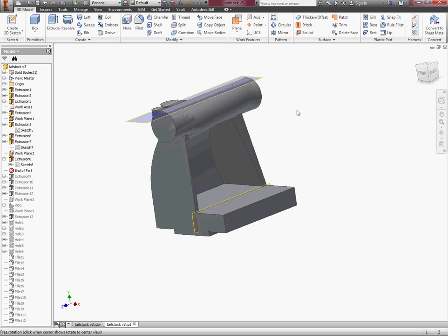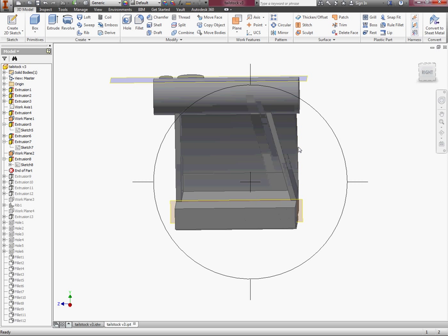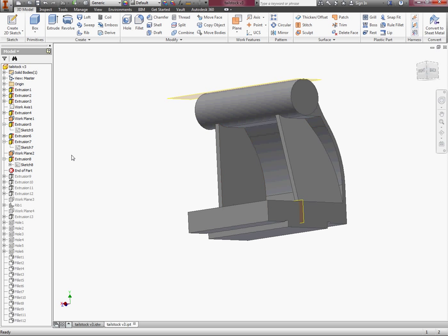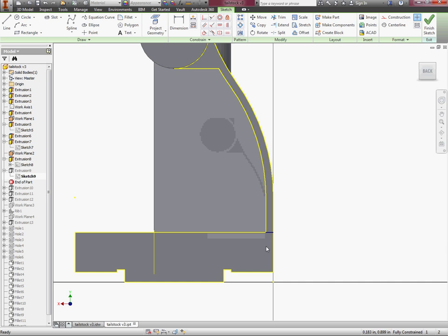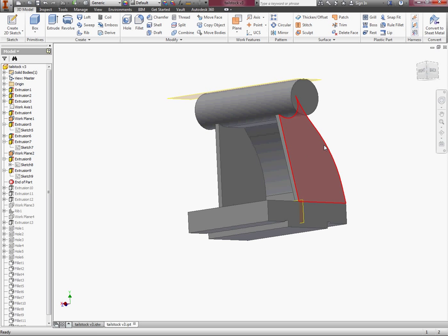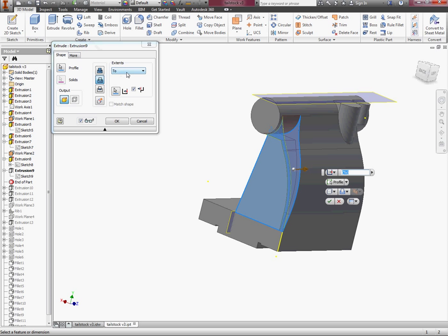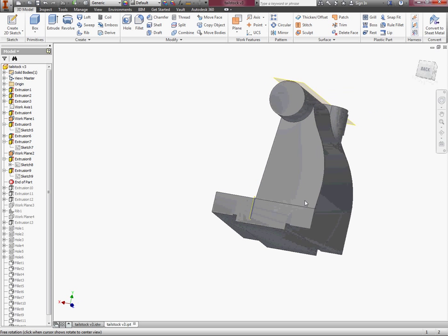Next step is on the other end here. If we have this angled end wall, we need to cut that area off. So we're just going to put a sketch on the end of this part right here, and all you have to draw in is this one little line, and then hit finish sketch. And what we do is we extrude cut, and we set our distance to 2, and you click on this surface right over here, that slanting surface, and it just removes everything along that angle, and it gives us this nice clean angled look over there.